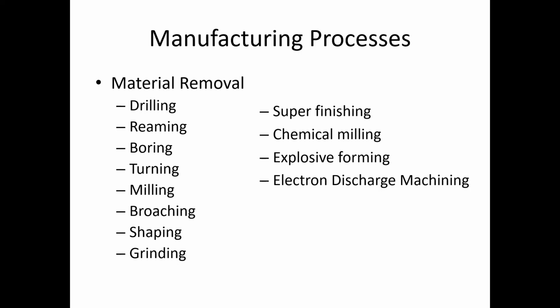So just kind of the primary difference between milling and turning. They're both material removing processes, common in machine shops. In turning, the material is going to be round bars, and the bar is spinning and the cutting tool is stationary and engages the spinning bar.